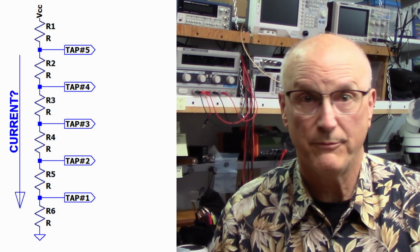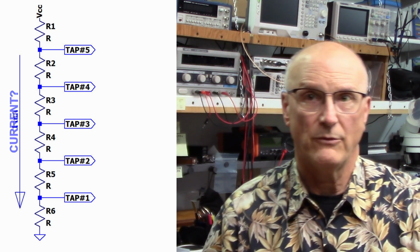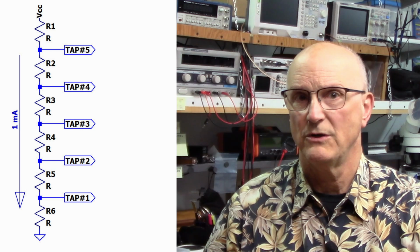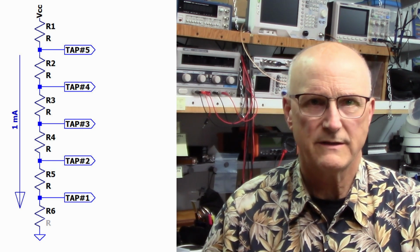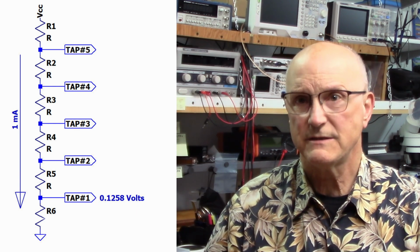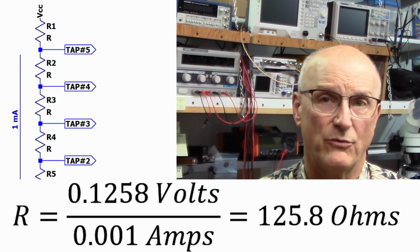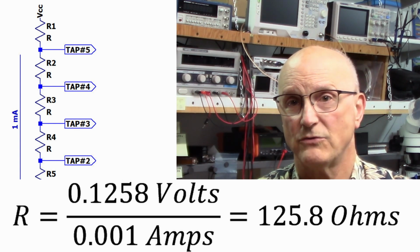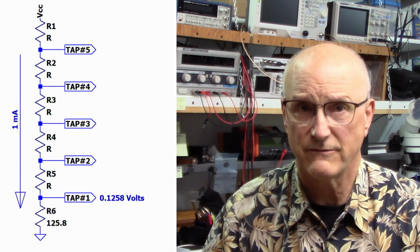The first step in its development is to decide on the current that we're going to be putting through the voltage divider. I will choose 1 milliamp, just like I did with the peak indicator's voltage divider. We start at the bottom and work our way to the top. The first voltage level that we're interested in is 0.1258 volts. This is produced across a resistor with 1 milliamp flowing through it. So the resistor value would be 0.1258 volts divided by the 1 milliamp, or 125.8 ohms.